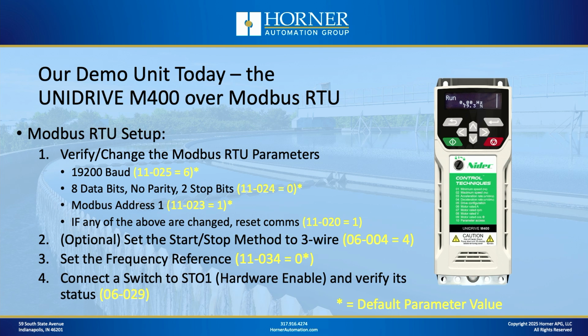And then you can verify you have got a properly enabled drive by checking the status in menu 6, parameter 29. So that's what I did as preliminary setup for the demonstration today.